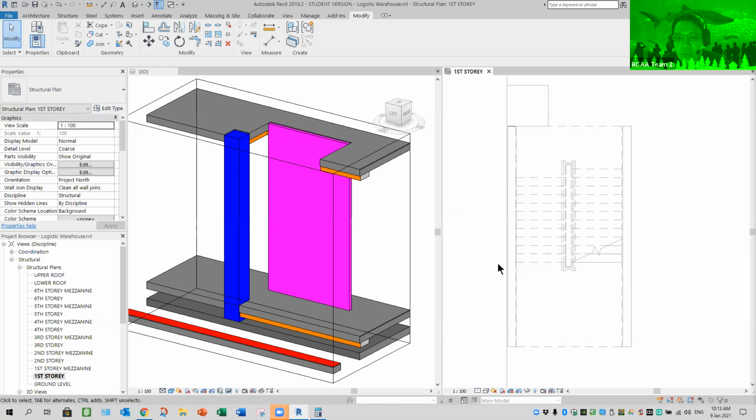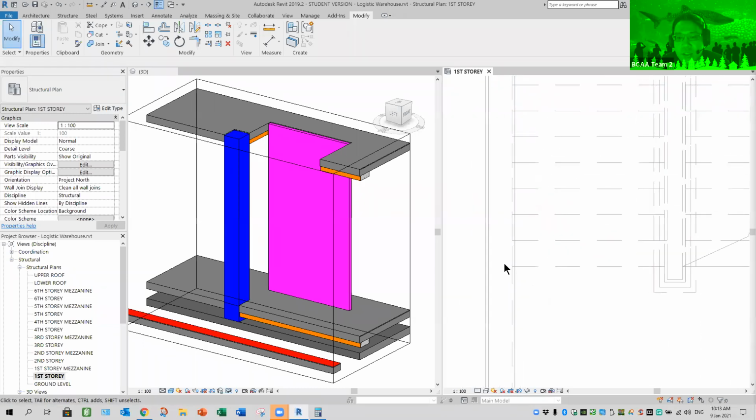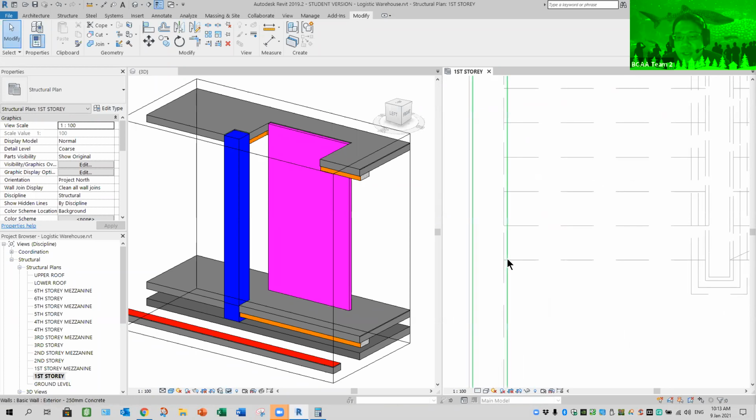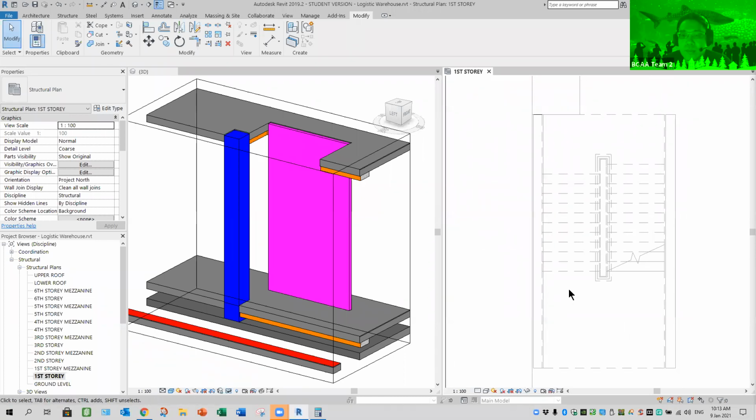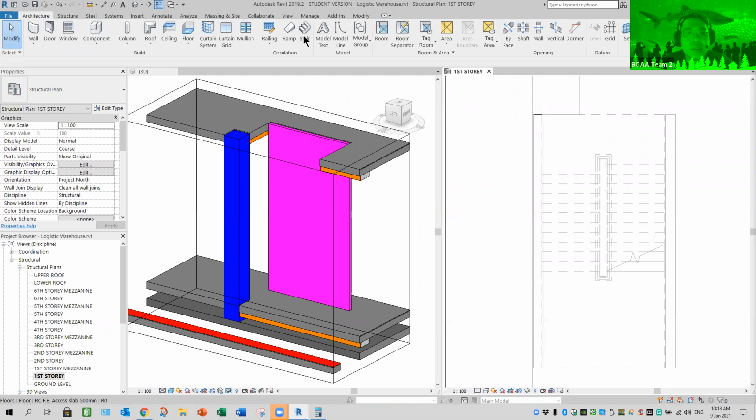But when you sketch, be careful. Don't follow blindly, because when the staircase is shifted in, there's an offset. Okay, so roughly we know the spacing, the gap we need. So the next step is to create your stair. So go to Archi, stairs here.